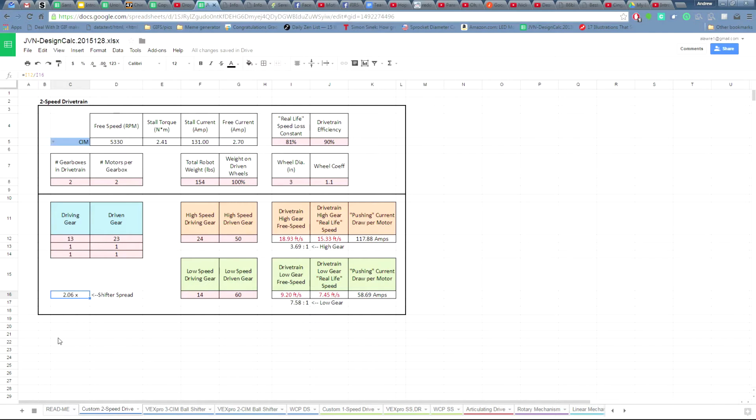Too high of a spread can be kind of useless because you don't want your speed to be so high that it's uncontrollable, and you don't want it to be so low that it's useless. So with a super large spread, you can have a very high gear and a very low gear. That's pretty useless. I found a spread around 1.8 to 2.0 is pretty good. Anything more, you really have to have a reason for your gears. But understanding what speed you should be per game is a different video altogether. So maybe I'll go over that later in a different video.